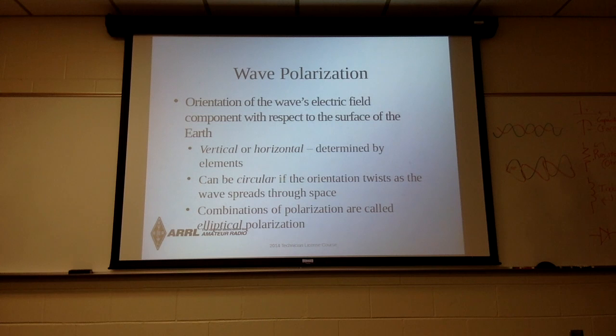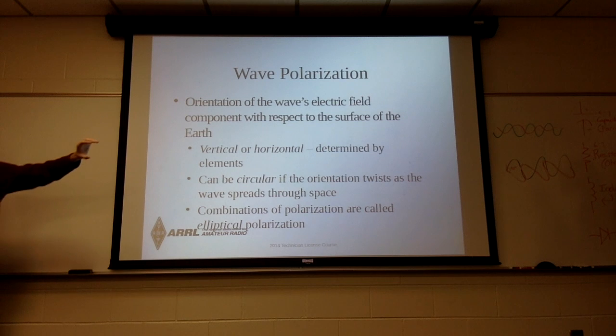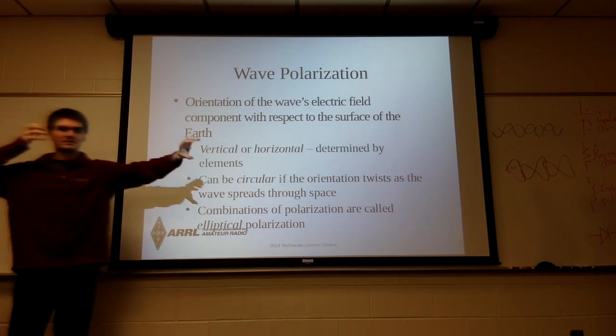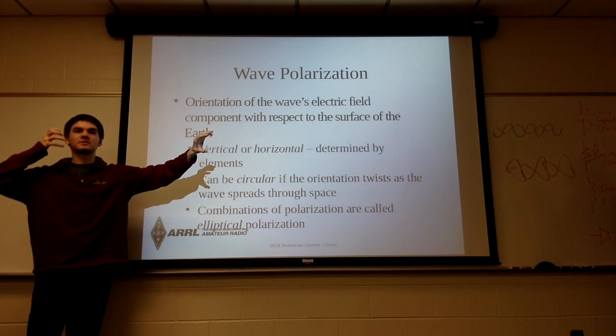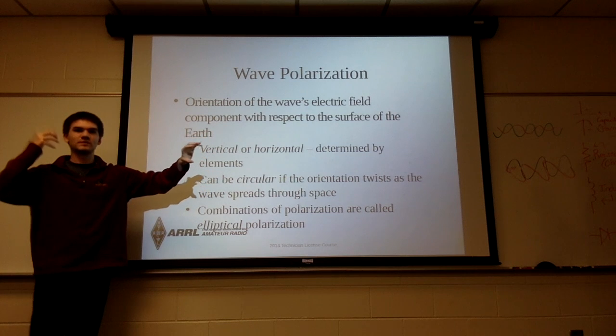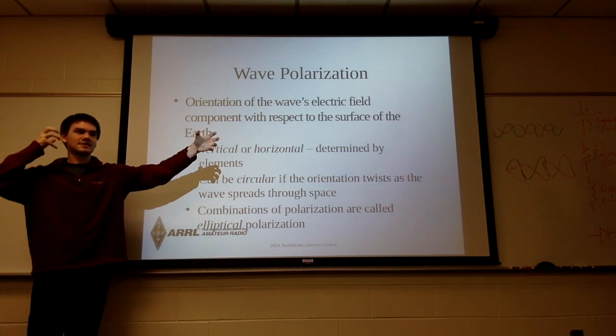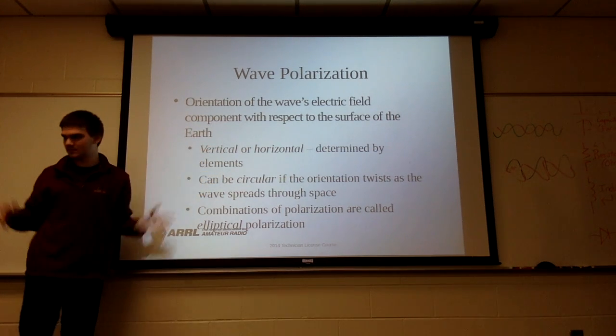There are several questions on the exam about polarization. I think the figure is something like 20 dB. Yeah, you lose a lot. So if your buddy in a field has a walkie-talkie held to its side, and you have your walkie-talkie up to your face like this, you won't be able to talk to each other for very far. You could probably do it in this room, but if you turned it the same direction, you'd be able to talk much farther.